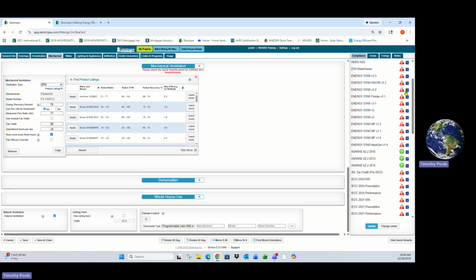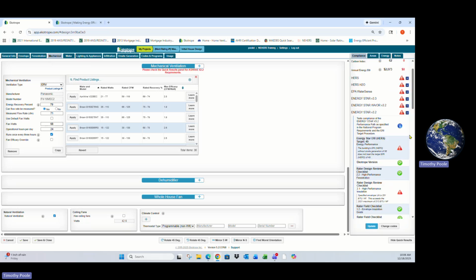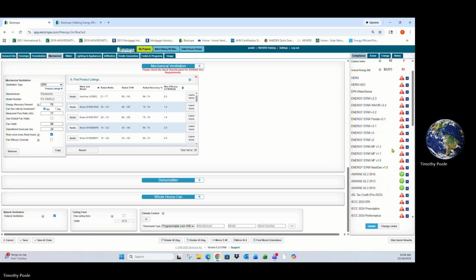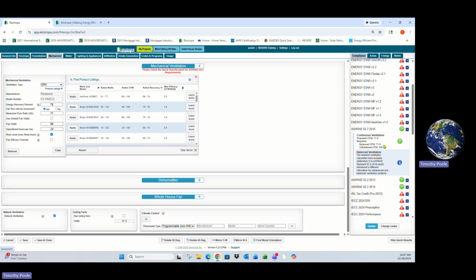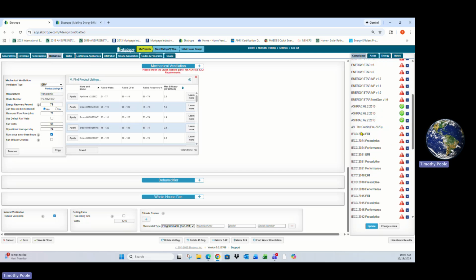Energy Star version 3.2, for example, what's missing from that, you can go through and verify what you need to edit. In this case, ASHRAE is a ventilation, so this also says our required is 71 and our proposed is 71, so we are right on target with our ventilation. But we're missing the mark for the 45L tax credit because there's not a 50% reduction in heating and cooling. That is based on the current home in comparison to the reference home.